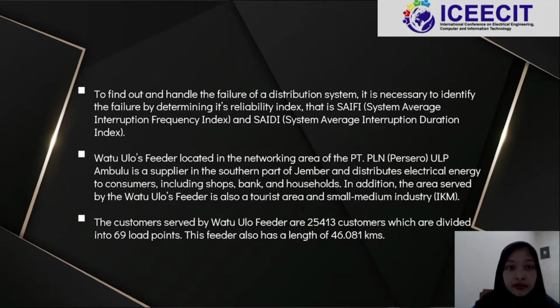And then, to find out and handle the failure of a distribution system, it's necessary to identify the failure by determining its reliability index, which is called SAIFI, or System Average Interruption Frequency Index, and SAIDI, or System Average Interruption Duration Index. Watu Ulo feeder is located in the networking area of PT PLN Ambulu.